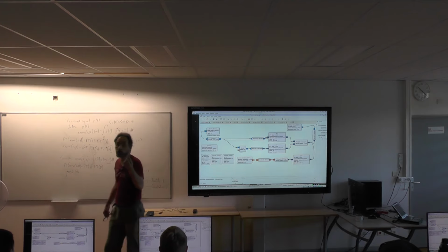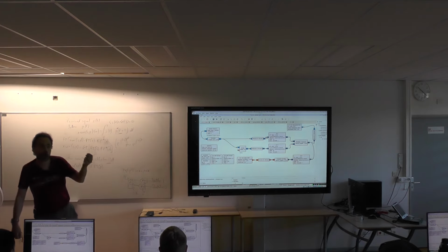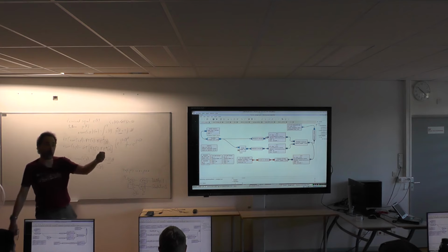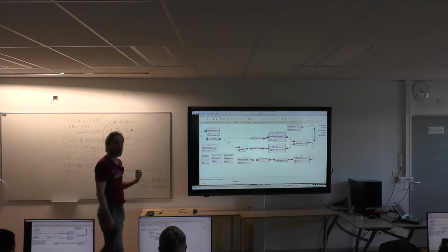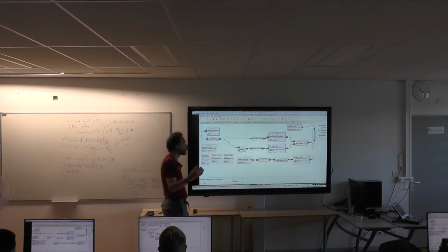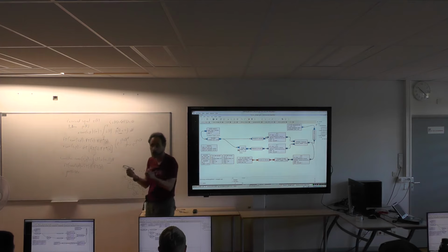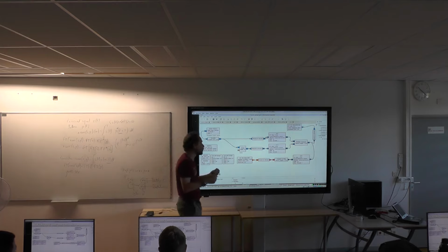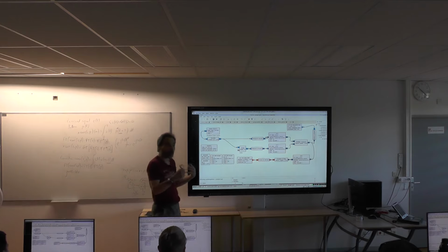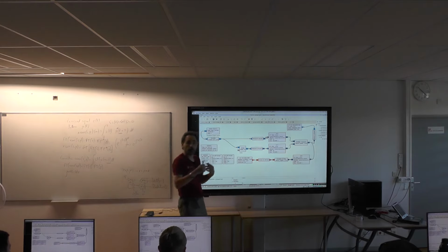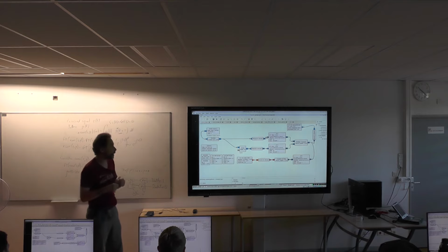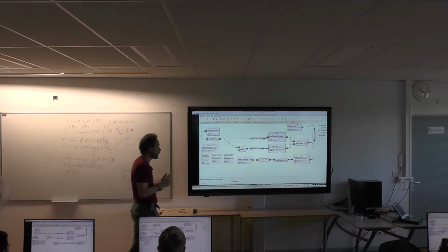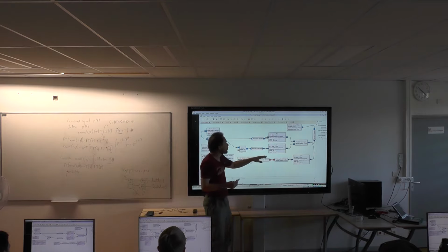This is also what I use when I'm developing noise radar. When you do noise radar, you generate a noise, and you're the only one to record the copy of the noise, so no one else looking at the spectrum can know that you're broadcasting a signal for ranging targets. But because you know the noise signal that you broadcast, you can look at the backscattered signal from the targets, and by cross-correlating, you can detect the various backscattering reflectors, which are radar targets. So in radar naming convention, this is the reference channel, this is the surveillance channel.